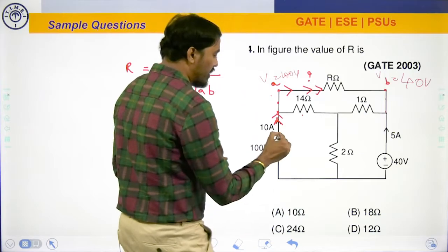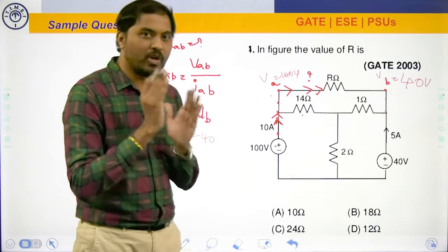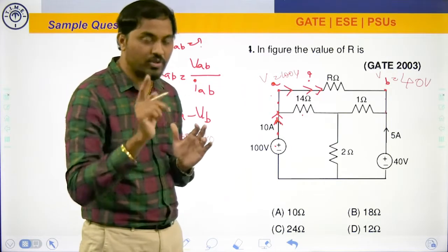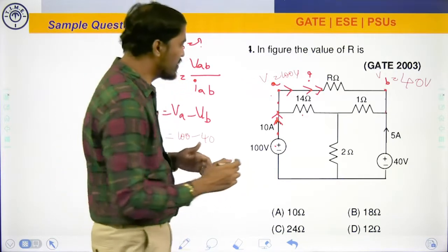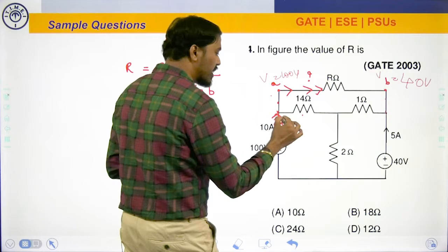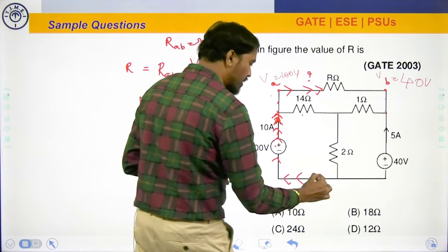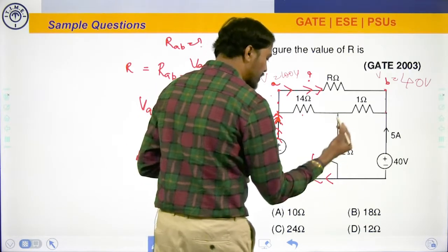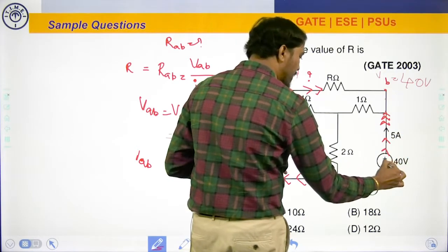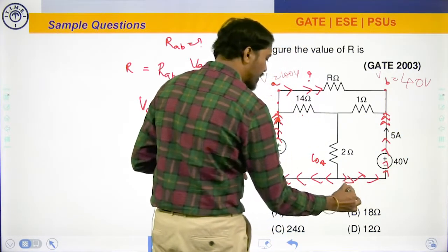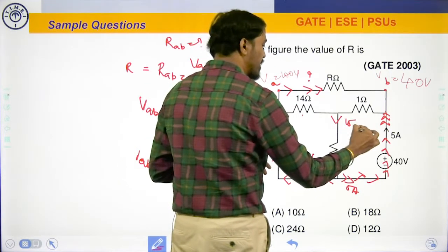Whenever currents are mentioned in the circuit, please trace their path, meaning from which point to which point the current is flowing. And remember that whenever current hits a junction, it is going to divide. So upwards the 10 amperes flow till here. Now let me come in reverse way. 10 amperes here. Next, 5 amperes is still here. Coming in reverse, 5 amperes. This is 10, this is 5, which means this is 15 amperes.